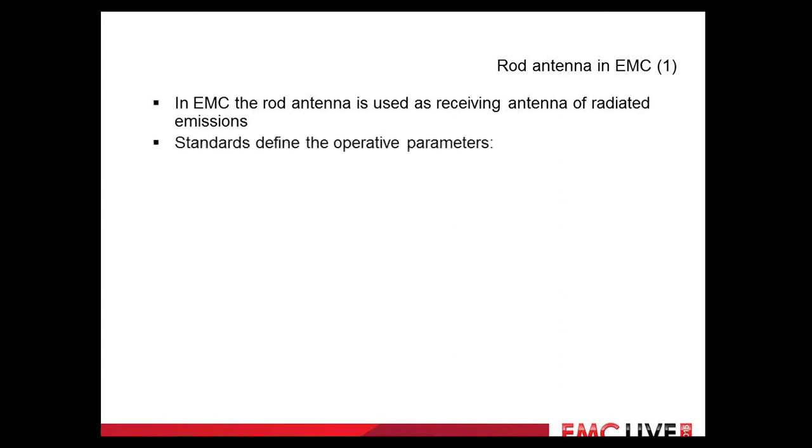defined by standards. So standards say the rod length must be 1 meter or 1 meter and 4 centimeters. They also state the counterpoise size, for example, 60 by 60 centimeters.